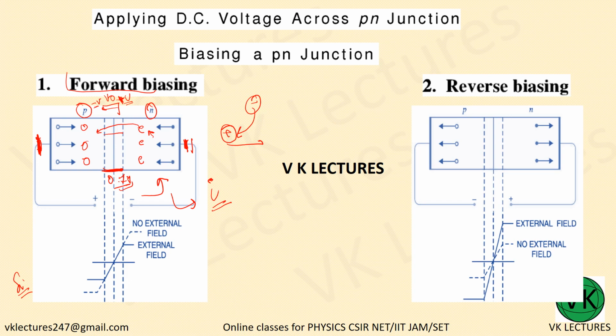So once it crosses 0.7, there will be no barrier against this potential we are giving the voltage. Once it crosses, it will have free movement across this, and as and when you start increasing the potential across this in forward biasing mode, then more and more electrons will start flowing to the other end, giving rise to current.